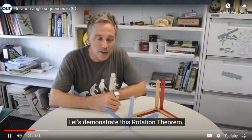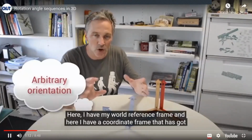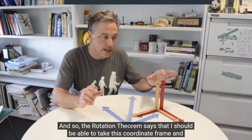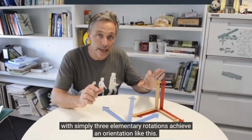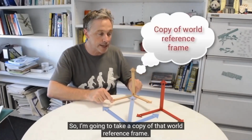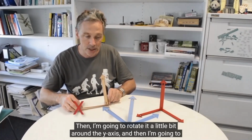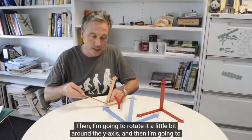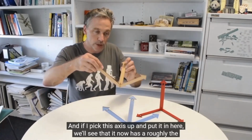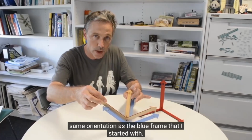Let's demonstrate this rotation theorem. Here I have my world reference frame, and here I have a coordinate frame that has got an arbitrary orientation in space. And so the rotation theorem says that I should be able to take this coordinate frame and with simply 3 elementary rotations achieve an orientation like this. So I'm going to take a copy of that world reference frame, and the first thing I'm going to do is to rotate it a little bit around the x-axis, then I'm going to rotate it a little bit around the y-axis, and then I'm going to rotate it a bit around the z-axis. And if I pick this axis up and put it in here, we'll see that it now has roughly the same orientation as the blue frame that I started with.